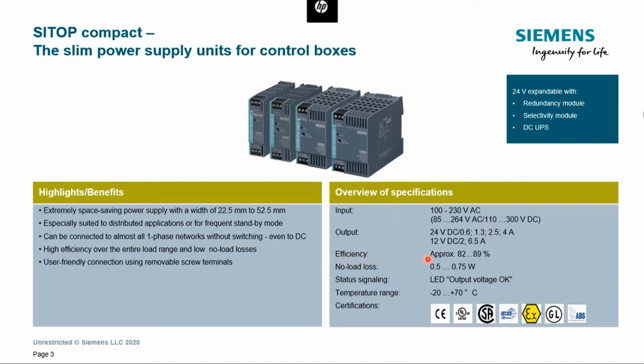Being a basic power supply, the efficiency is not the best, up to 89%. Still good, but we will see better performance. In terms of diagnostics, it does not have any remote diagnostic capabilities, so it gives you only visual diagnostics via an LED to indicate that the 24 volt output voltage is okay.